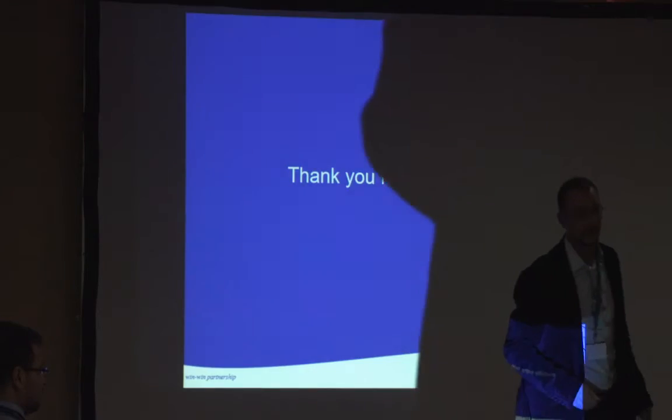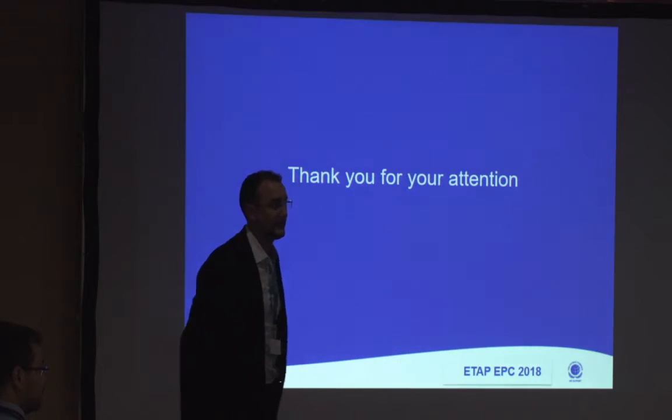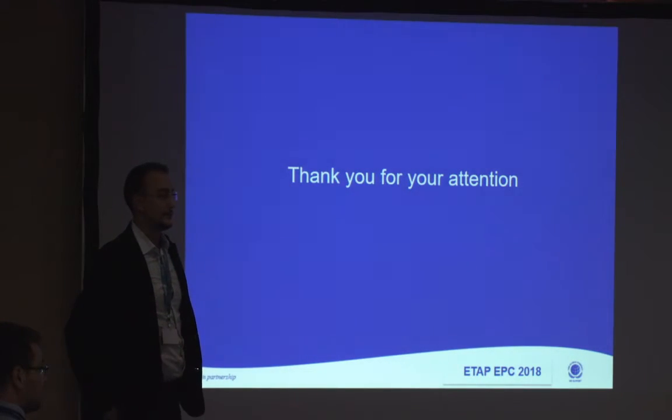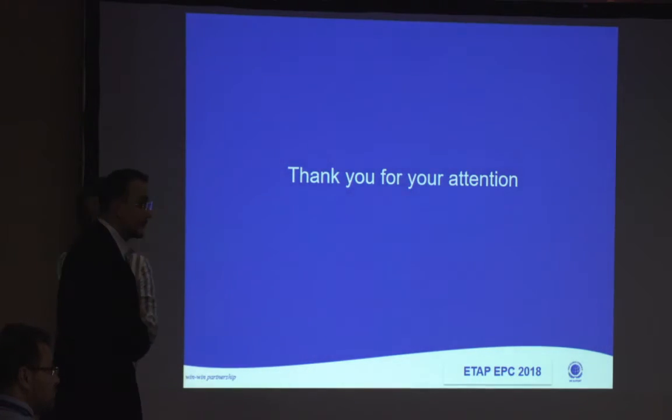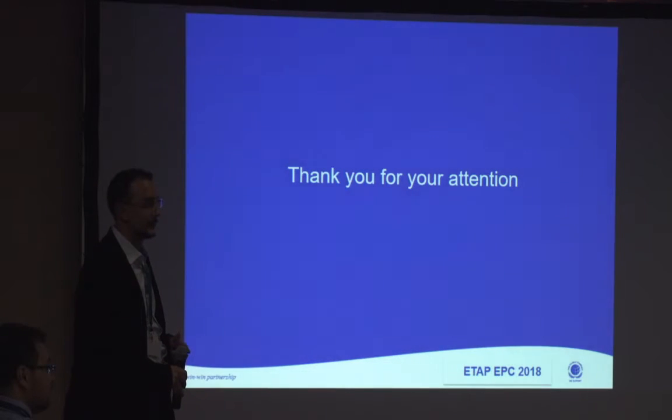Thank you for the presentation. My name is Boubacar Hamadi from Schlumberger. I have two questions for you. The first one is, I don't know if you have tried to create any phase envelope, to see how much liquid loading you have in the well. Before you go for foam injection, did you do any studies related to the evaluation of the well, the calibration of the well, and see the PVT, the phase envelope, and the line of the liquid loading, etc.?